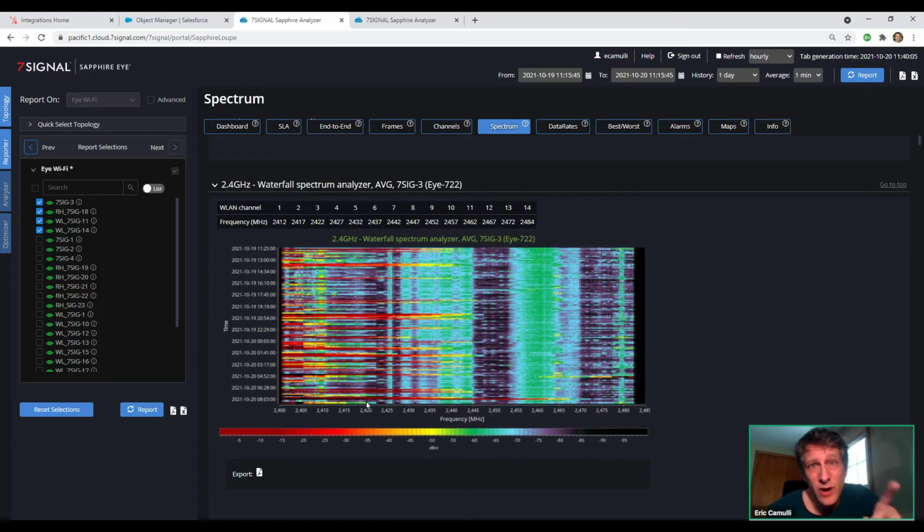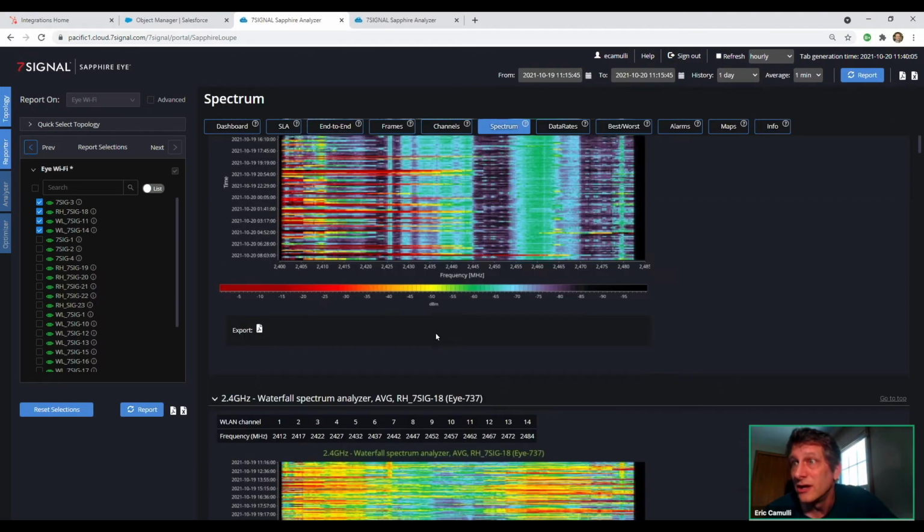The reason I don't think it is, is because normally I would see, over here on the right side, guys, the BLE advertising channel for Bluetooth. We also see that little thin stripe from top to bottom here. If it's Bluetooth interference, I usually see those light up red also, indicating that there's Bluetooth in the air. But when I see this here, it scares me. It's a little bizarre, basically rendering channel 1 and probably channel 6 pretty much unusable. All right, let's keep going.